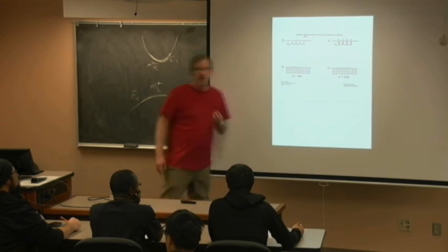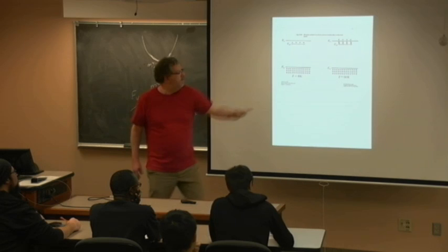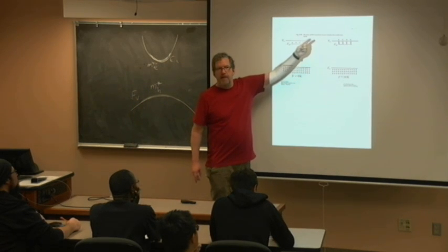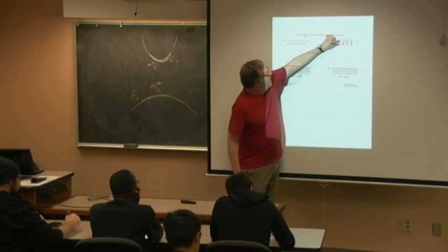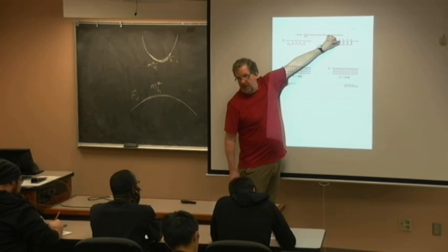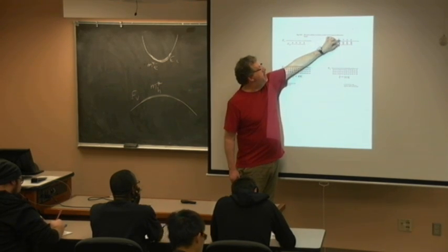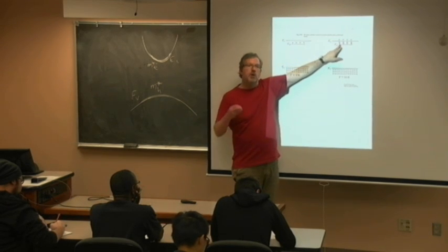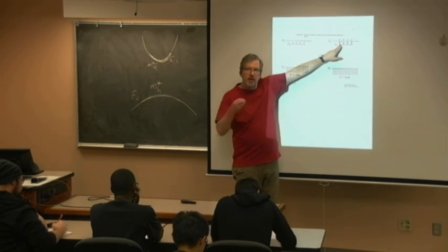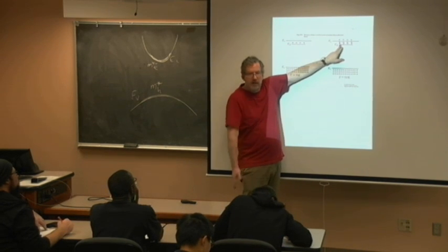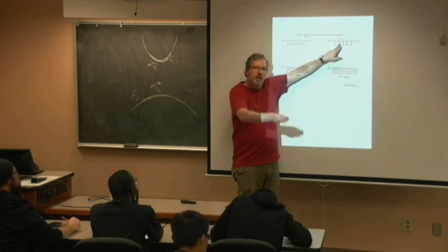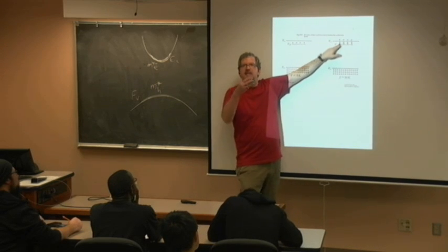What's the criteria for a good dopant for this guy? I want it to have an energy level where its activation energy is modest, so it's fully ionized at kT. I want it to be able to go into the lattice substitutionally, right? Because if I can't put it there, then it's of no consequence. And when I put it there, the third criteria is I want it to stay there.